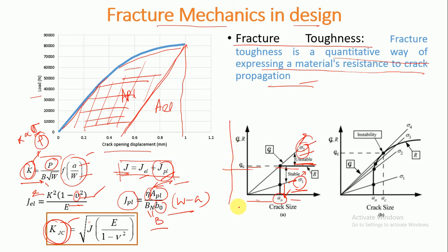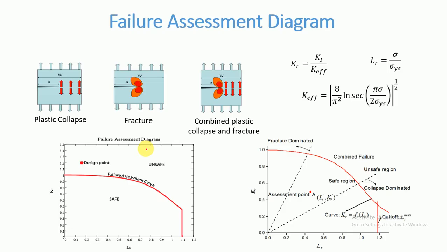In that way we can decide what the failure load is. And similarly for the elastoplastic case, we can get the resistance curve, which is a non-linear curve, and in the same way we can get the instability point.